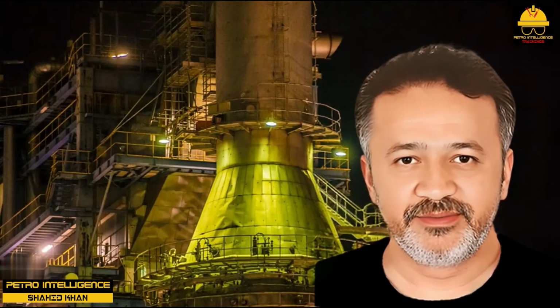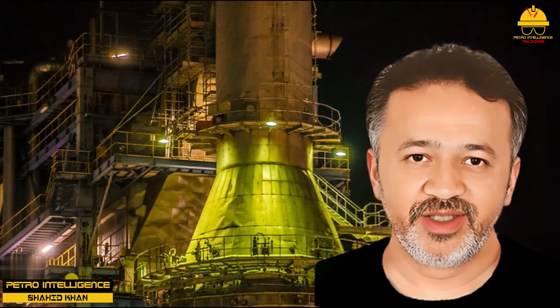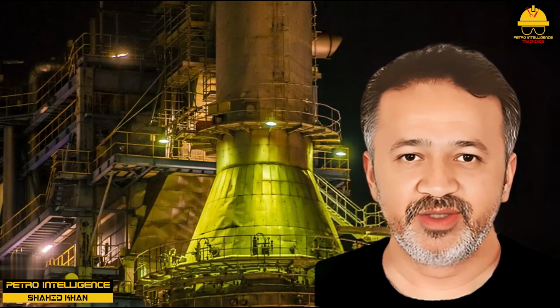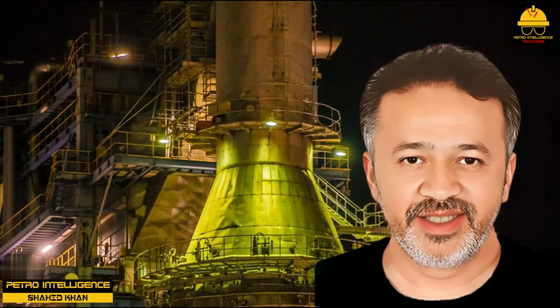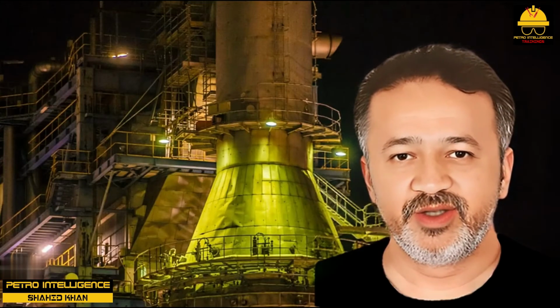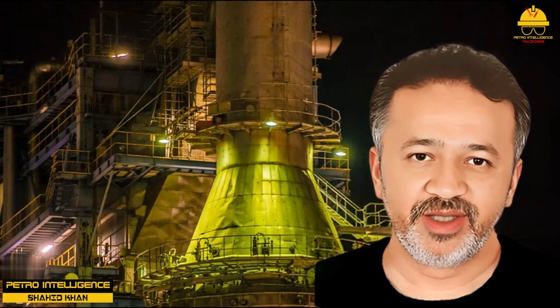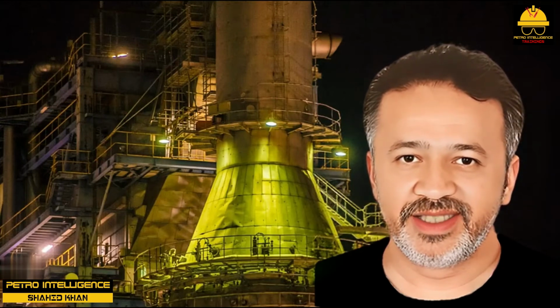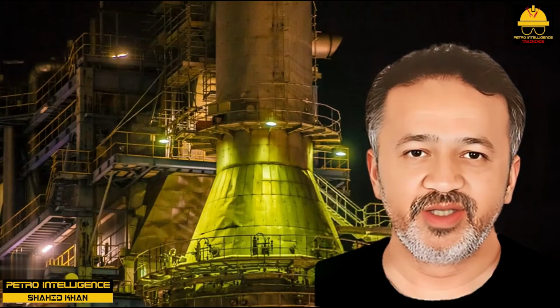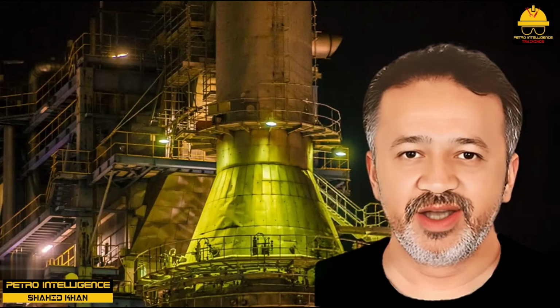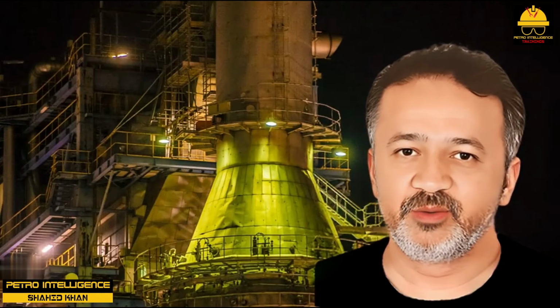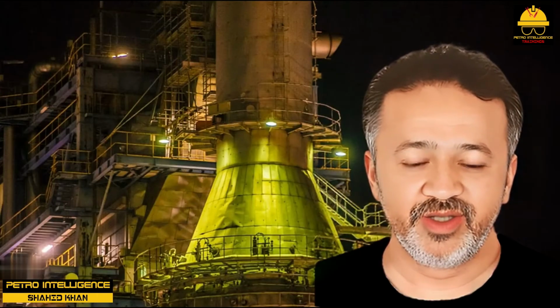Oxygen starvation. If you try to operate a fired heater with too little combustion air, you will starve the burners of oxygen to smother or bog down the firebox. Then you will likely cause afterburn or secondary combustion in the stack. You will not be able to operate on automatic temperature control, and you may even destroy the equipment altogether. This type of operation can also be described as operating on the wrong side of the point of absolute combustion.